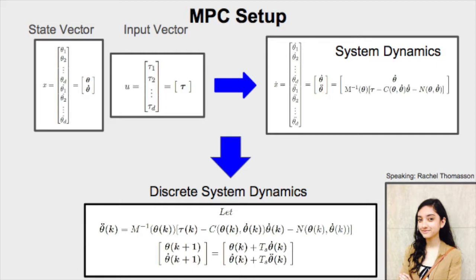We want a fast, effective, and safe controller. We had the choice to control the position of the end effector in Cartesian space or the input torques to the 7 motors in the arm, but decided ultimately to control the input torques because we had direct access to current, and controlling for Cartesian position could potentially be a further detriment to our runtime due to the need to run more inverse kinematic calculations per time step.